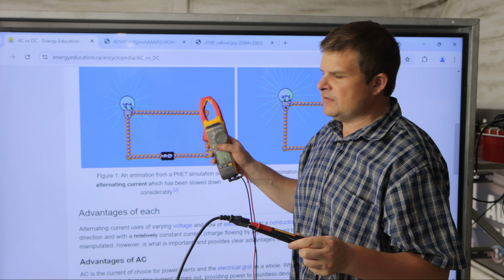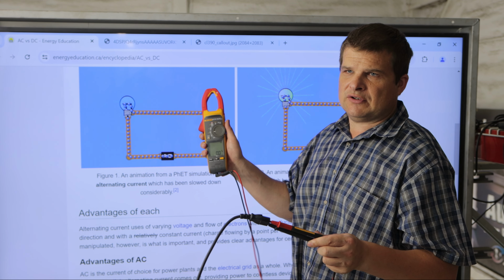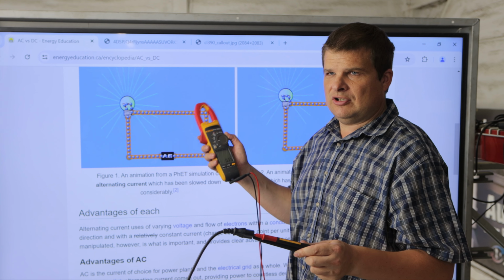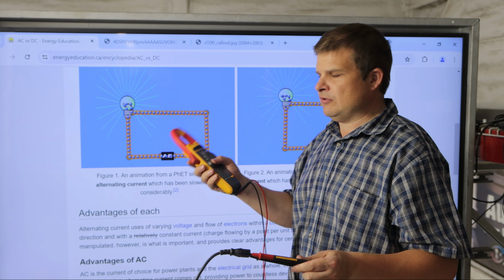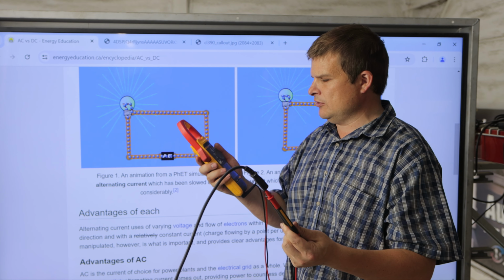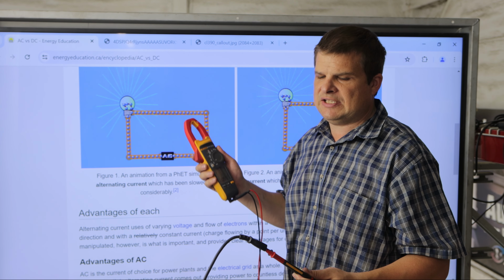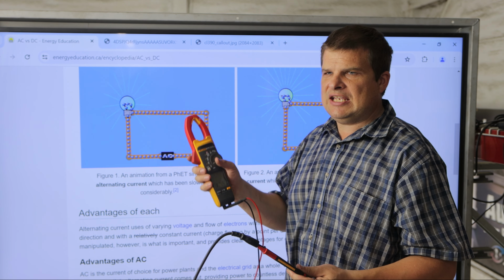I moved to here to DC. So on DC, we get 0 volts. You're like, man, I really need to know what I'm doing. Yeah, you need to know if you're looking for AC or DC. There's no direct current in this wire. It's all alternating, so you only get a measurement on AC. So there, now you know how to take AC measurements.